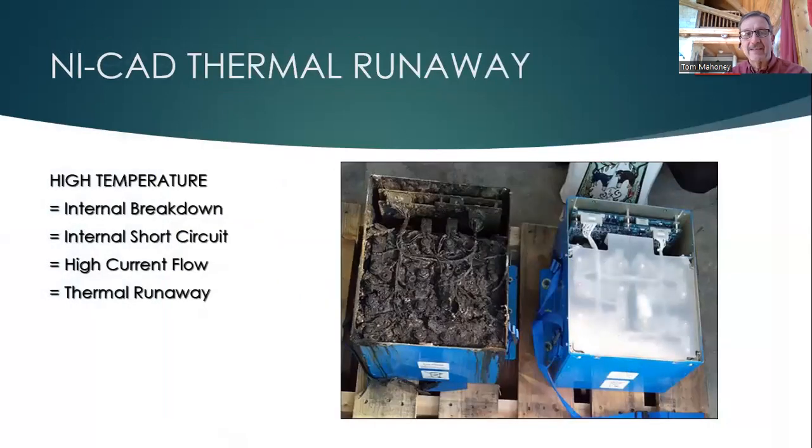This is the disadvantage, a NiCad thermal runaway. As you can see, it would not be a good day. Here's a battery that probably came off, who knows, a 737 possibly. And you can see that it had an internal thermal runaway and it melted it. This is what it should look like. You can still see the circuit board. And this one right here, there's the circuitry for it right there. So somehow this battery did not run away, but this one could have caught the airplane on fire.